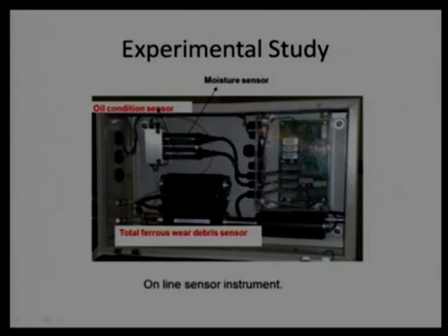Similarly, there is a possibility of corrosive wear. So, there is a moisture sensor. The moisture sensor clearly indicates if the relative humidity is very high, then we should not conduct the experiments, because a major governing factor will be corrosion, and there is a mechanical action. So, there will be corrosive wear.